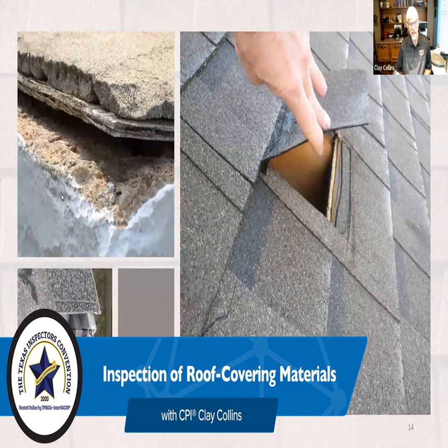Well, some of the materials in the shingle itself, some of what makes that shingle, can get hot and then they almost explode and they blister. That shingle is one that should be replaced. If I see a condition like that, report it.